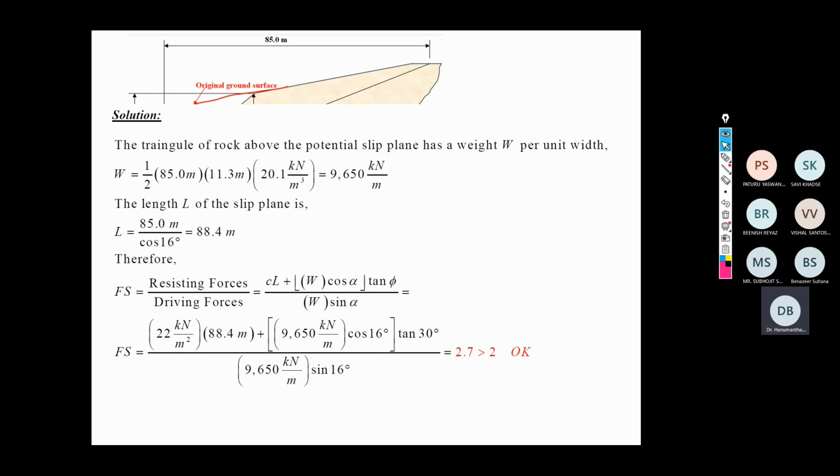While such may not be the case in a homogeneous material like soil, because that is a progressive failure. While there are two contrasting materials, because of the contrast in their properties, they will accelerate the failure. That is why, wherever there are two contrasting materials, we normally consider a higher factor of safety value.